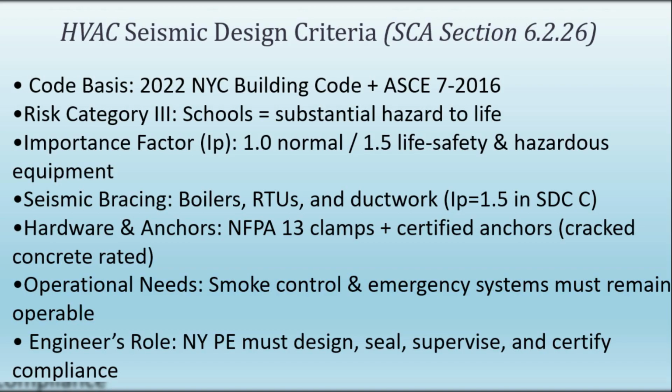Finally, a New York licensed professional engineer must design, seal, and submit restraint calculations, supervise installation, and certify compliance with an affidavit. In short, Section 6.2.26 ensures HVAC systems in NYC schools are not only efficient, but also safe and resilient against seismic events. By setting strict codes, assigning responsibility to licensed professionals, and requiring certified equipment, the SCA ensures that critical building systems can withstand seismic events without putting students or staff at risk.